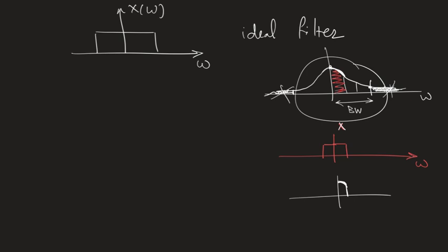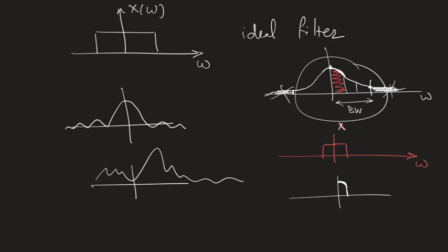Now, I want you to look at this. When you do this operation in frequency domain, you know that what you did here by multiplying your signal in frequency by this filter is that you picked this particular frequency range of your signal to do something with it, okay? Now try to imagine how this would look like in time domain. This square in time domain is a sinc function, right? Okay, and your signal in time domain is this guy, right? Whatever. And then in frequency, the multiplication corresponds in time to convolution.